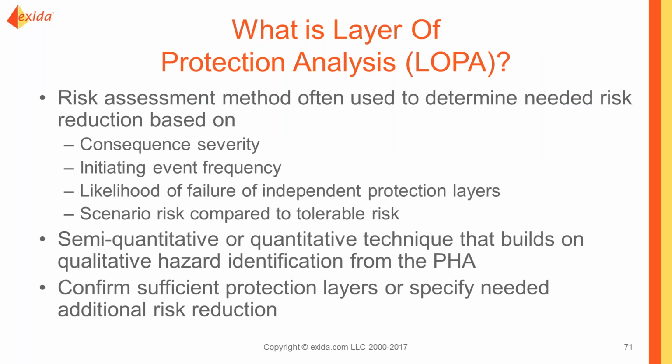So another quantitative way to do this is a layer of protection analysis. And I would say that both of the techniques we just looked at are semi-quantitative approaches. Each of those decisions or things we took credit for are essentially pseudo layers of protection. So a layer of protection can be done semi-quantitatively, and so semi-quantitatively, for example, you might determine specific protection layers you're going to allow the team to take credit for, and you may do them on an order of magnitude approach.